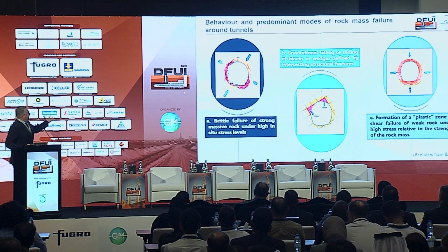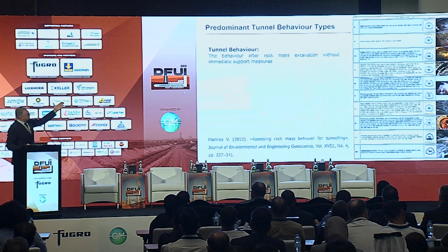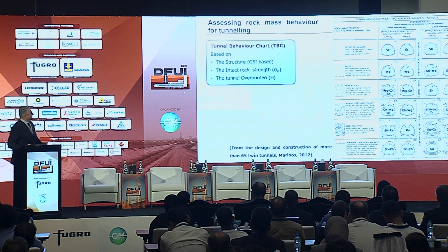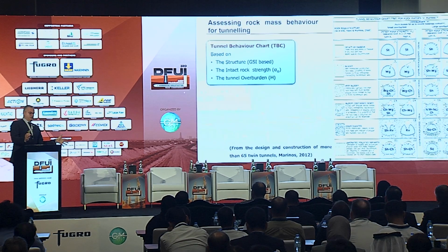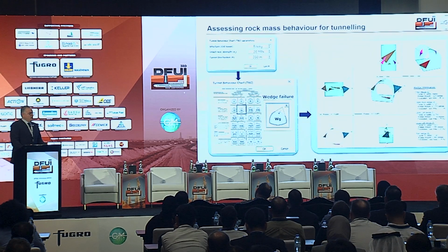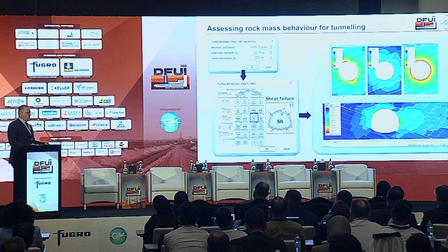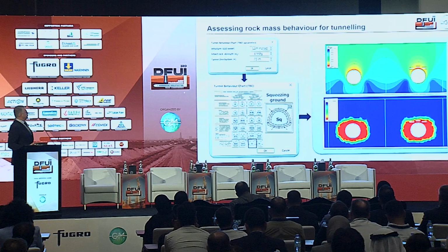So from brittle failure to structurally controlled or squeezing, we can have numerous rock mass behavior types, and you can assess this from the structure of the rock mass. You need to see the structure of your rock at the scale of your project, which needs experience, together with the small or large overburden, and of course your intact rock strength. And then this behavior can tell you what kind of analysis to proceed with: structurally controlled, anisotropic or discrete element analysis, or squeezing, an isotropic one.